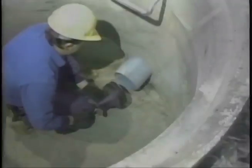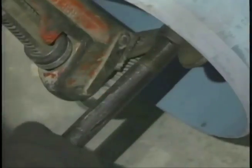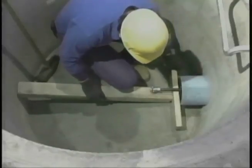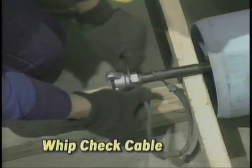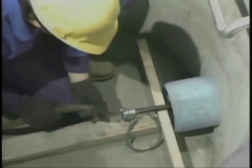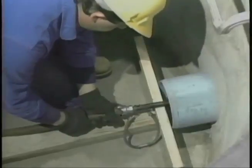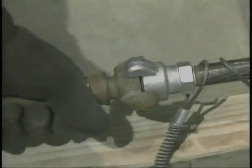To begin the test, place a plug in each end of the line and tighten securely. Brace the plugs at the ends of the pipe. Attach a whip check cable to the plug end. Then connect the airline hose. Once connected, slide the cable loop over the end of the hose.